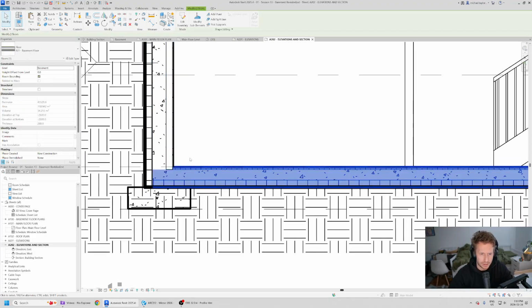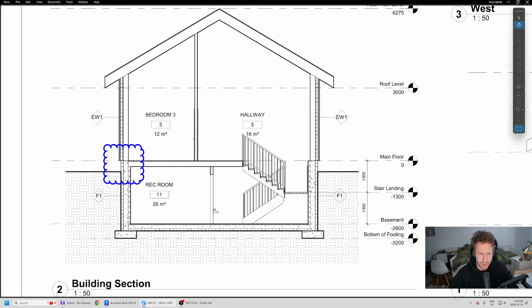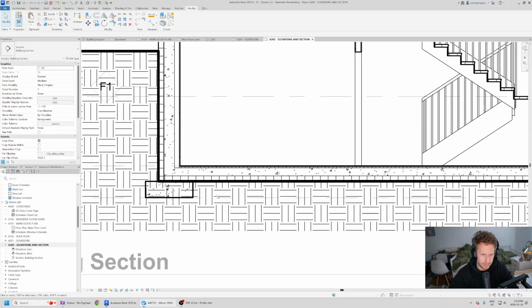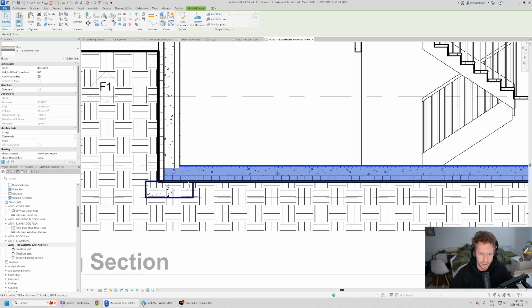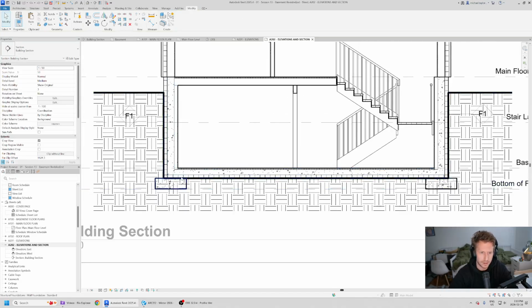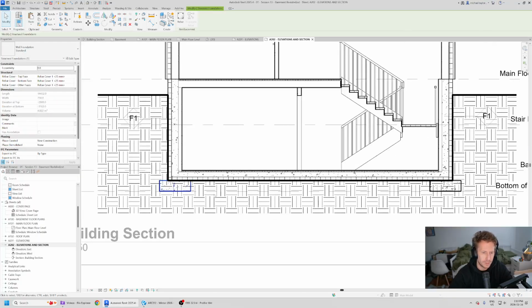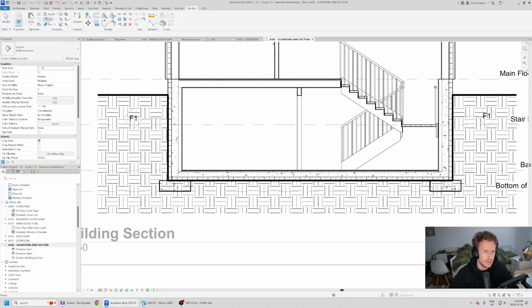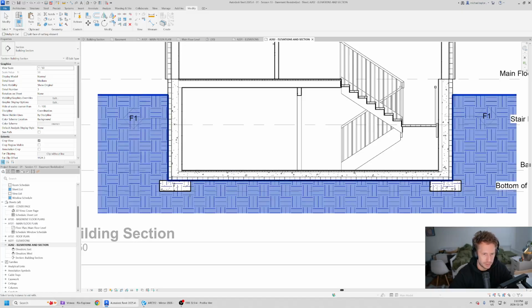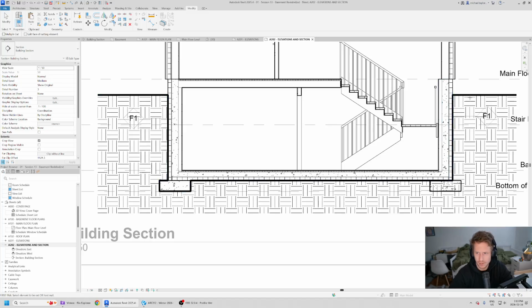I actually think that I'm going to unjoin these, and we'll fix that up, because I think that I want my concrete to sit on my foundation, which of course makes sense, but Revit isn't quite as smart as everybody in this class. So first things first, I want to cut this out, but it doesn't look like it's going to let me. So let's see what we got. We're going to cut, select element to be cut. So I want to cut this using this. Aha! Okay, it will let me do that.